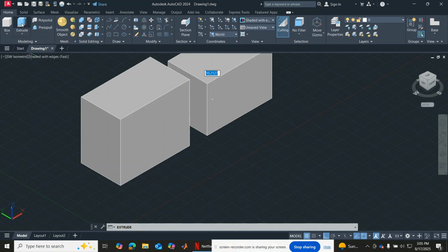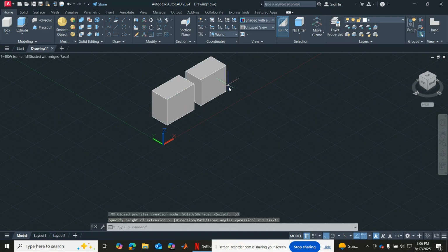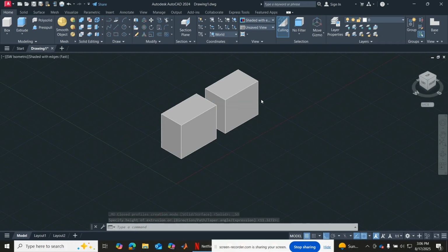So when I extrude that, it will be a fully solid 3D feature. So say extrude. So you see now it's an extruded solid feature like that, not a hollow surface, because I joined the individual lines to make one entity. Okay?